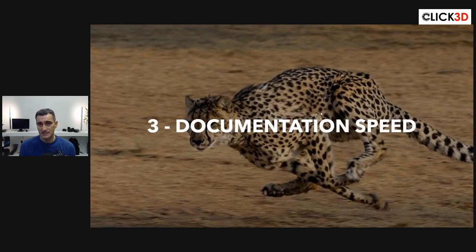So if you have to cover a wide area, laser scanning is going to take a very long time. Especially if you have a wide, long stretch of space, like a long straight roadway. The laser scanner just can't jump from one spot way down to another spot. You try to keep the scans relatively close so that they can connect, and you have a series of scans that get registered together. So that takes a bit more time.